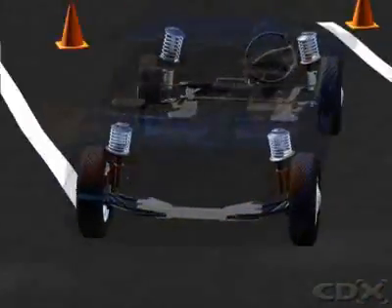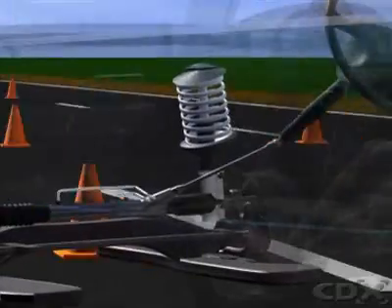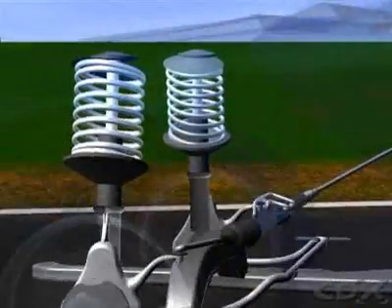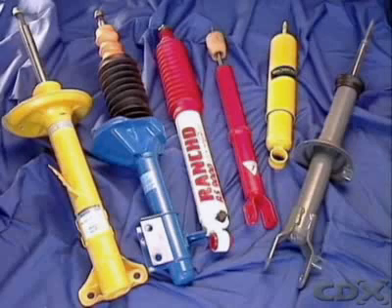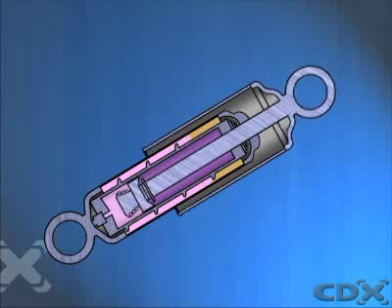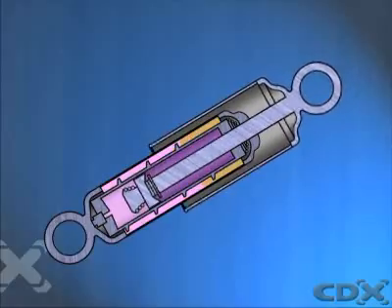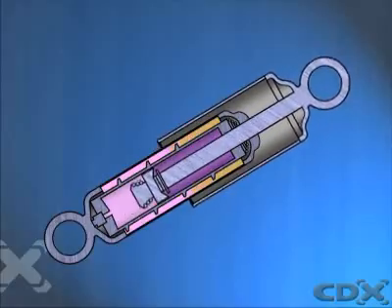Shock absorbers have a marked effect on how well tyres follow a road surface. They damp the natural bounce over the road and reduce spring oscillations. There are different kinds of shock absorbers, but they all use a piston sliding in a cylinder filled with oil.